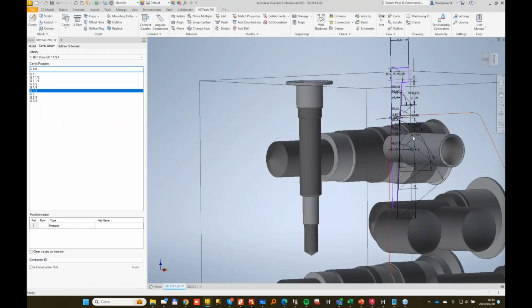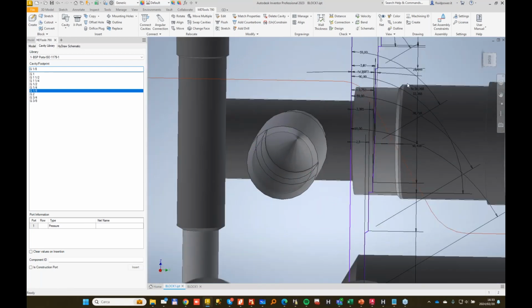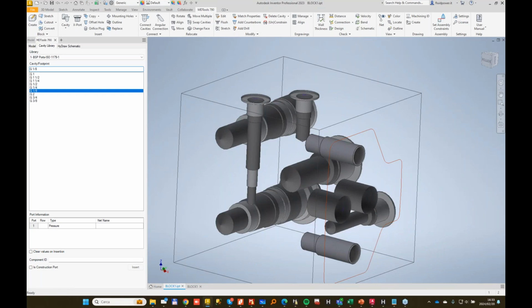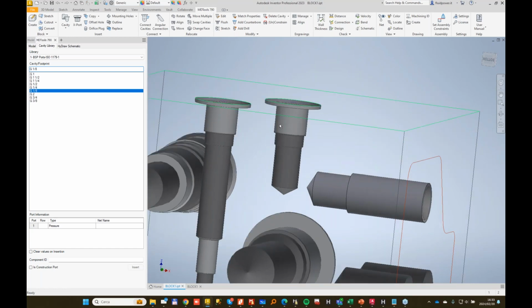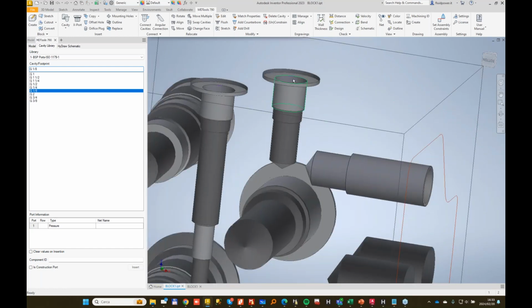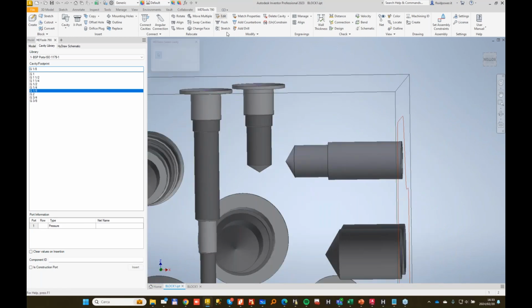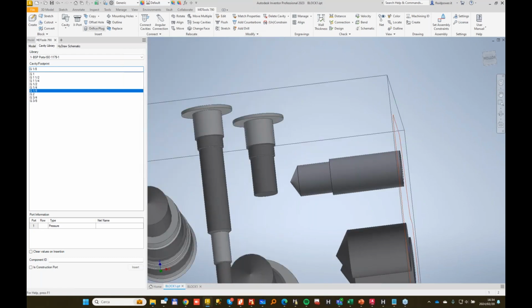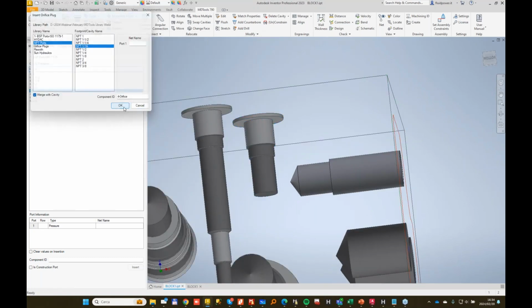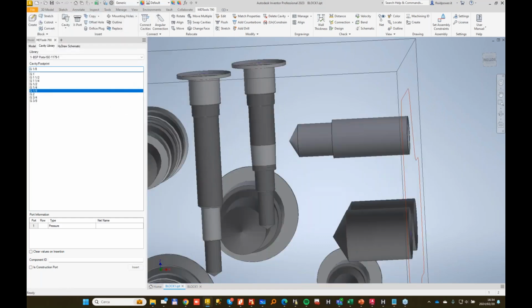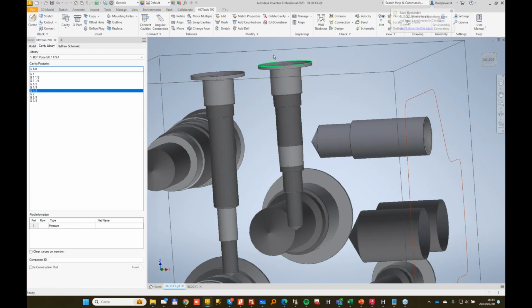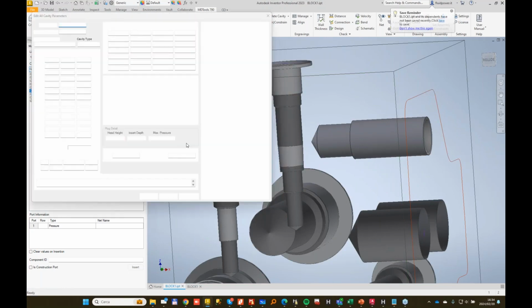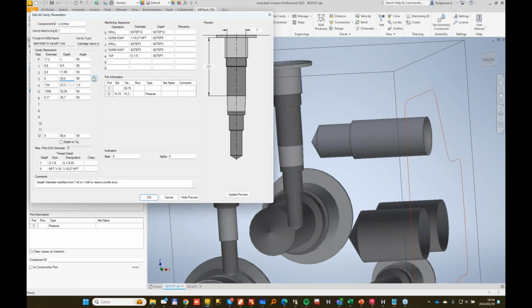It's not always happening, but it means that there is some problem with the sketch definition of this block. As a workaround, and this also solves another problem for the precision, if you want to add an NPT, NPTF 1/16 in a cavity, first change the angle to 90 and then add the orifice plug. That's just a workaround, it will work. And the other advantage of this is that you will really be able to control the depth of that NPT port more efficiently, because then it's a precise position, and we can make it 30.